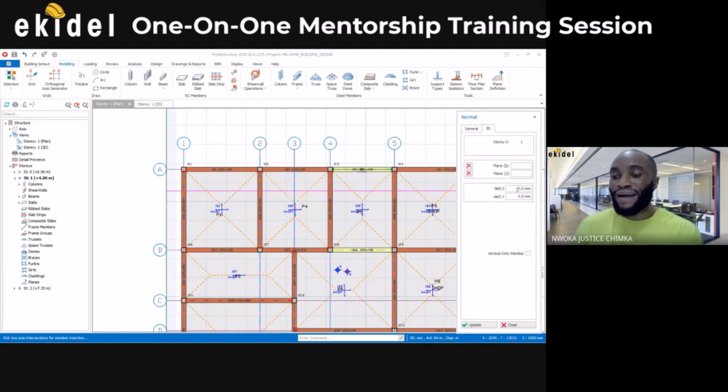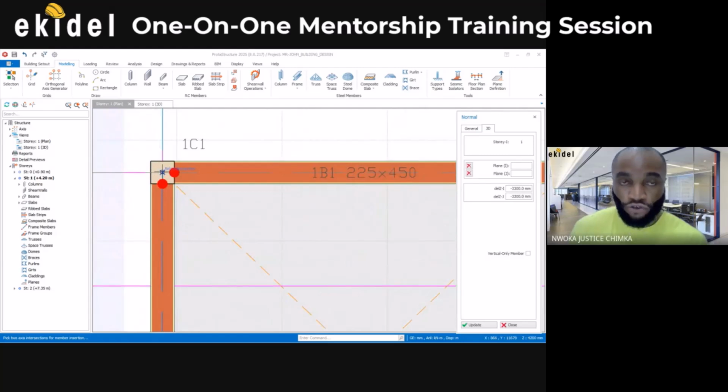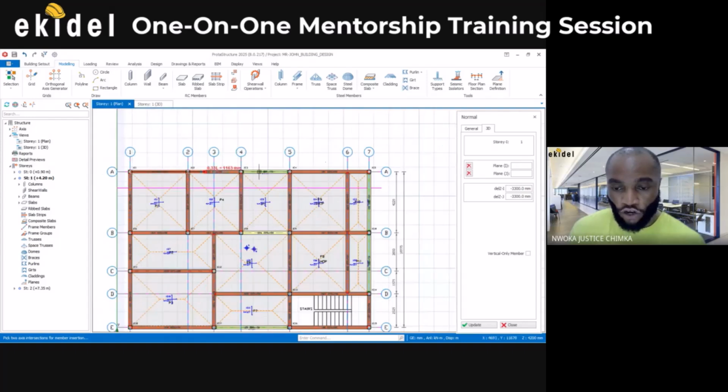Now I define the level of that beam, which is this DZI and DZJ. So I'll come and put minus, meaning that it should send the beam to minus 330, which is the level of the last floor, the last level of that story. Yes. I'll come again here to minus 3300, and then insert, just the same way you normally insert a beam. Click on this, and then I have the beam running all the way down to this level.